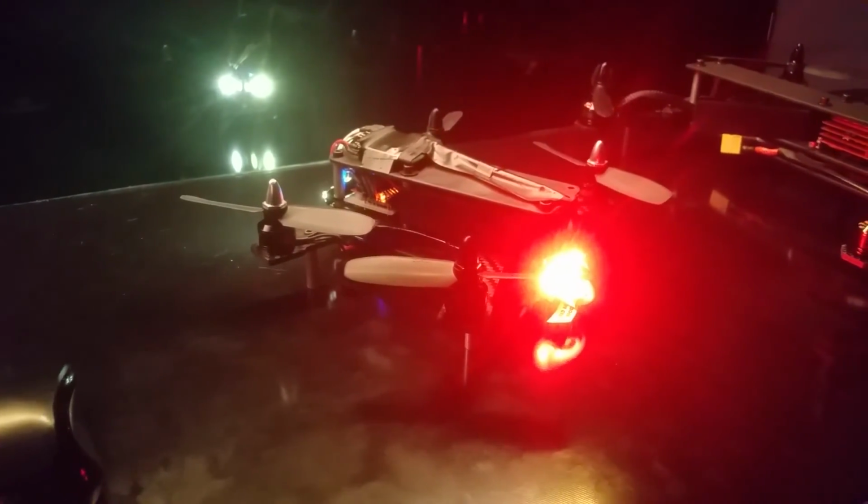Okay, so you saw it fly. One of the things I wanted to mention, the difficulty I had was I would design a control law, and even though it looked good in simulation, because the motors have an output maximum, a certain thrust, and because the sensors have a certain amount of vibration they can take before they just get too noisy, I had to limit the bandwidth, half the bandwidth I really wanted. It's not going to be a big deal in the end, but in this case, maybe if I dampen the sensor more, then it might help a bit.